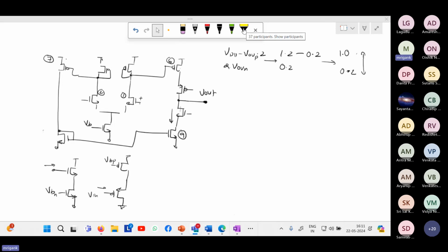Yes. So when your input voltage is going towards a lower value, it will be turned off, because your NMOS will require some VGS, right? So this VGS plus V overdrive, the VDS of the NMOS 2. So this NMOS stage will turn off for output voltages which are less than VGS of 1 plus VDS of 2. So for V out less than this, the output will be clipped.